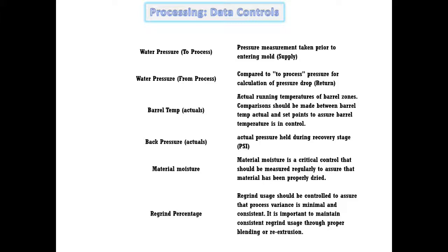For instance, if you have pressure going in at 50 psi and the pressure coming out is 40, then you know that the water is passing through pretty freely, little restriction, good flow. Now, if you had the same condition of 50 psi going in, but the water coming from would be at 20, then you know you've got pretty serious restriction and you might need to make some corrections.